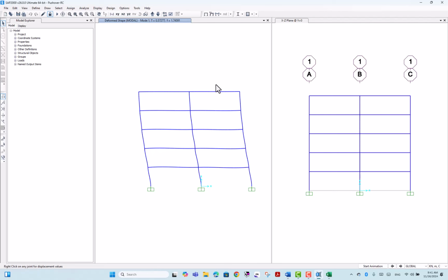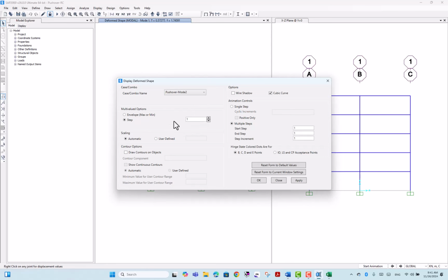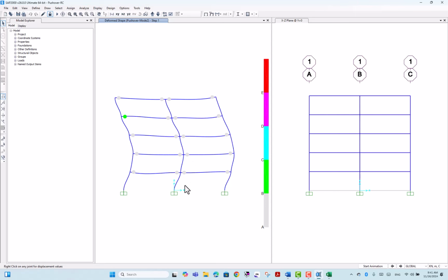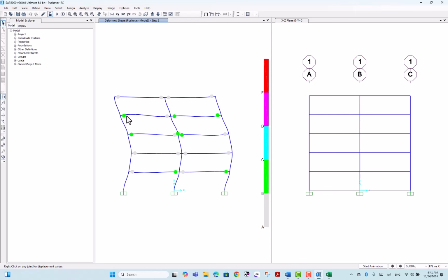And if I go to the second mode, you can see the second mode is totally different, and the top beam is actually deformed. When we push the structure while it's in a specific mode shape, like bending or torsion, the structure will experience significant loading.